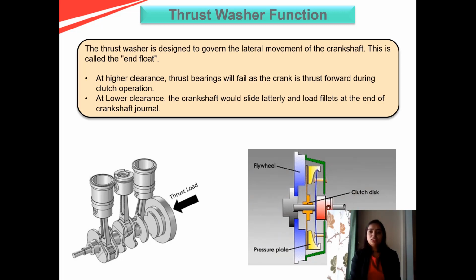If clearance is on the lower side, during the thrust load, crank will go and load on the fillet on the crankshaft journal, and again it will lead to the crankshaft failure.